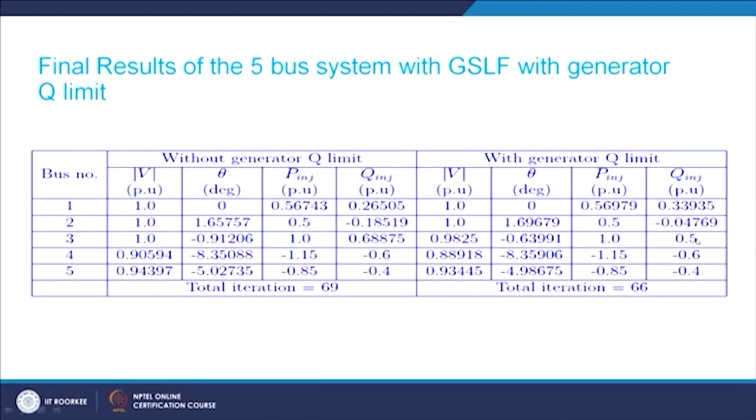Same thing also here. Here our total effective reactive power load is coming out to be something like 100.4 MVAr, but the total generation by the generators is only 83. So, the rest, that is 17 to 18 MVAr of reactive power, is being generated by the shunt charging susceptances of the lines.